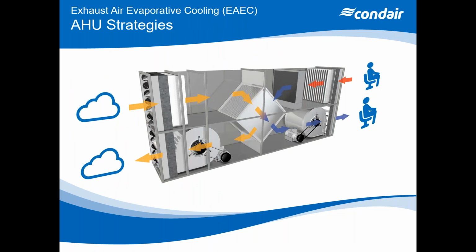Now, you may have an application where we require a large amount of fresh air, but still want to use evaporative cooling. When you come across that application, we then switch to exhaust air evaporative cooling. We still want to utilize evaporative cooling, but again, we've got a high air exchange rate. We don't want those high humidities either.